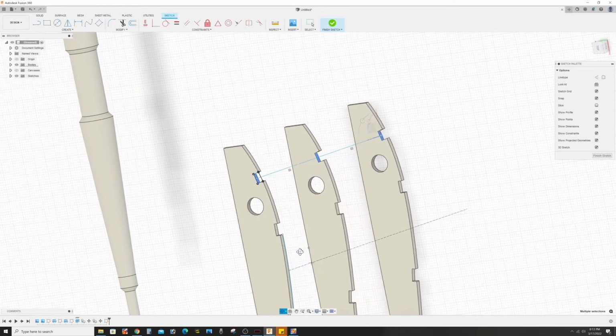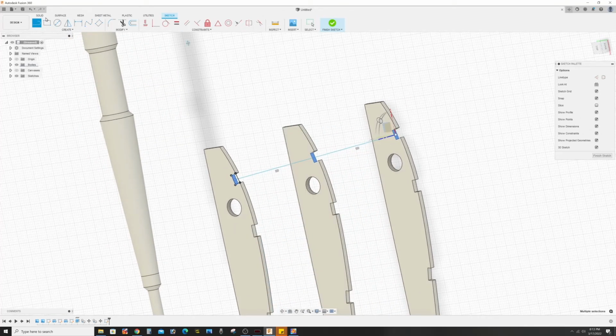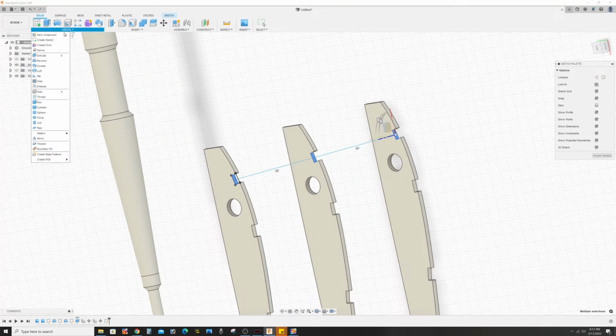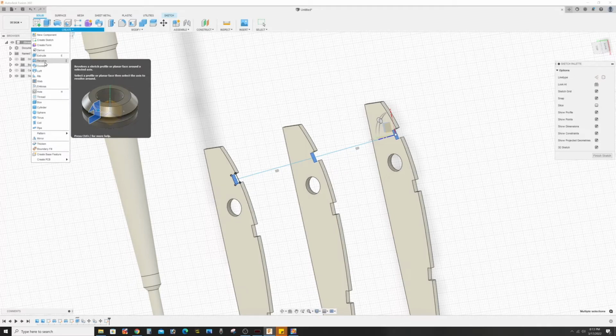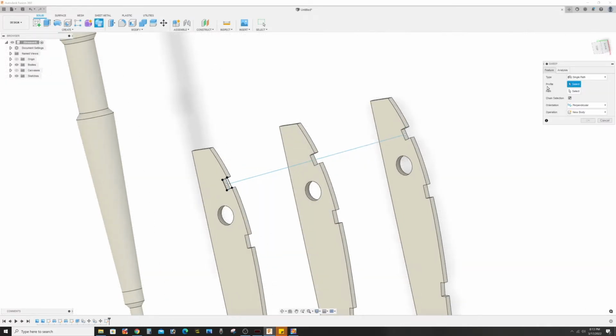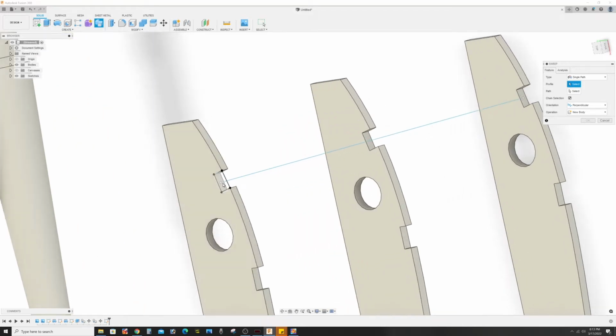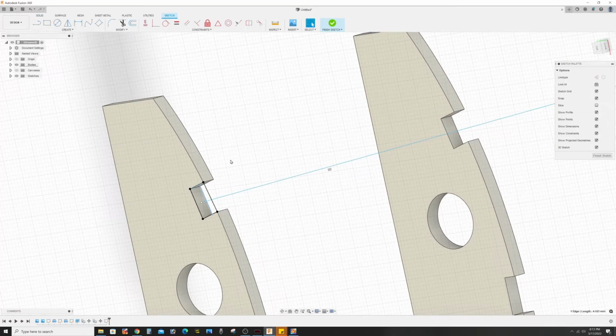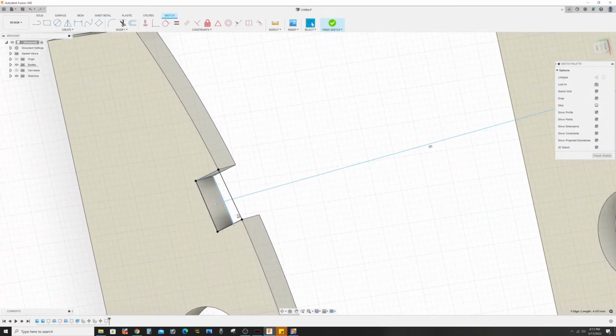You can see it, right? It's all on the same plane. Okay. So come up to solid, create, sweep. Now follow the commands. It's going to ask you to pick a profile, which is the square, like a cross section. Is this not? Oh, I must have missed the line somewhere.